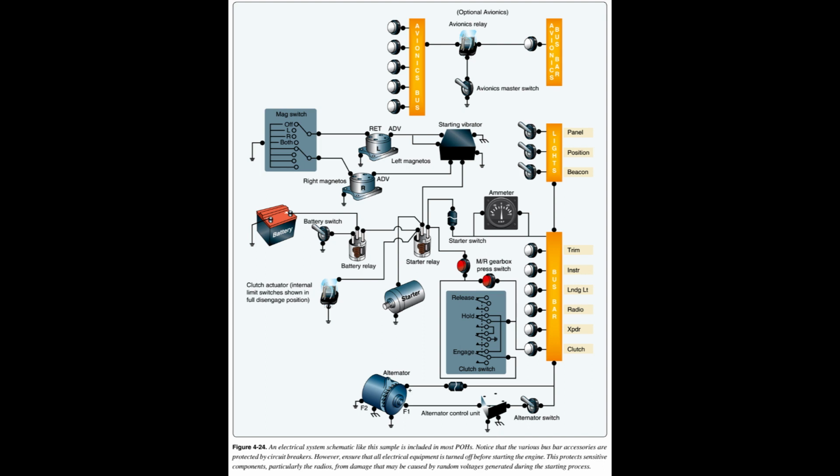A battery is used mainly for starting the engine. In addition, it permits limited operation of electrical components, such as radios and lights, without the engine running. The battery is also a valuable source of standby or emergency electrical power in the event of alternator or generator failure. An ammeter, or load meter, is used to monitor the electrical current within the system.